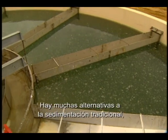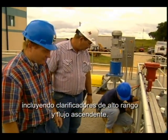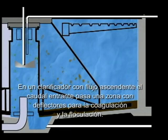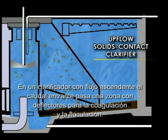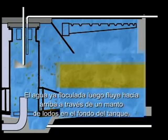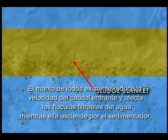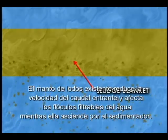There are many alternatives to traditional sedimentation, including high-rate and upflow clarifiers. Some processes combine coagulation, flocculation, and sedimentation into one basin. In an upflow solids contact clarifier, the influent is passed through baffled zones for coagulation and flocculation. The flocculated water then flows upward through the sludge blanket at the bottom of the tank. The existing sludge blanket reduces the velocity of the incoming floc, in effect filtering floc from the water as it travels up through the basin.